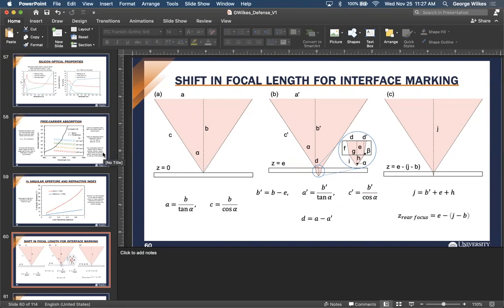I see. But that is because the silicon has the absorption tail. So just in case you use a wide bandgap material like gallium nitride, do you think you still need to focus it? If there's no absorption tail at this 1550, do you think it would work to bond without the focusing? Yeah, probably. I think it might work. You need a significant laser power or fluence to. I see. Or at least reduce enough temperature.